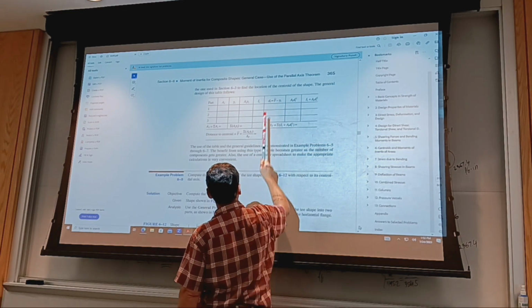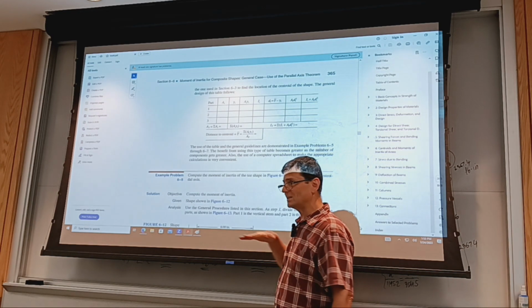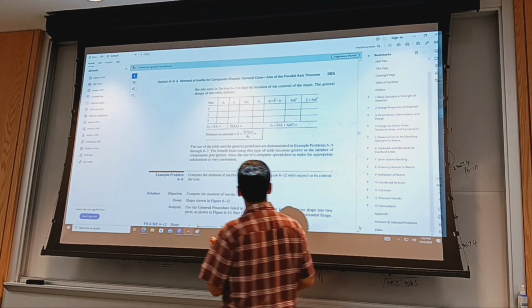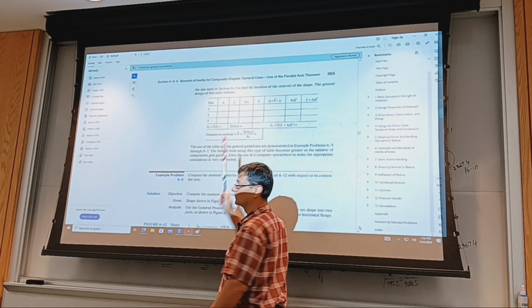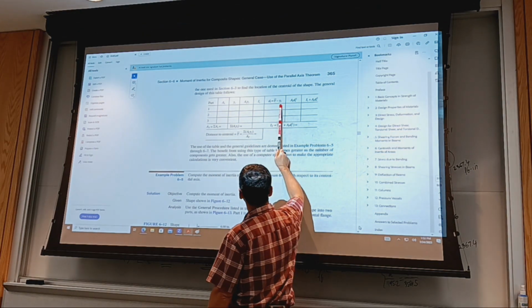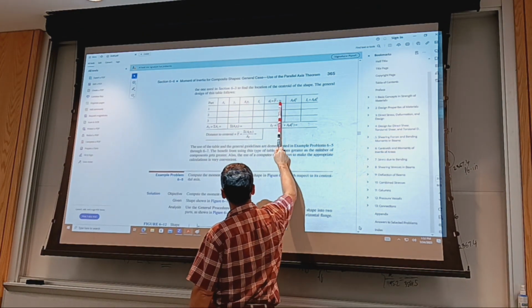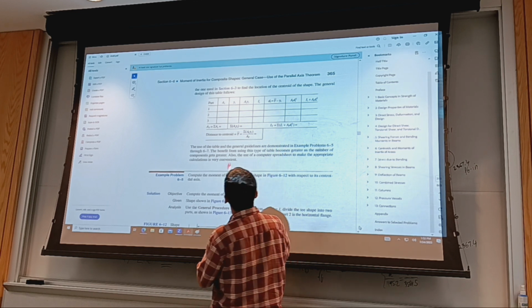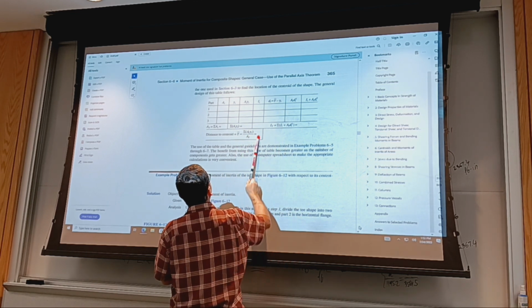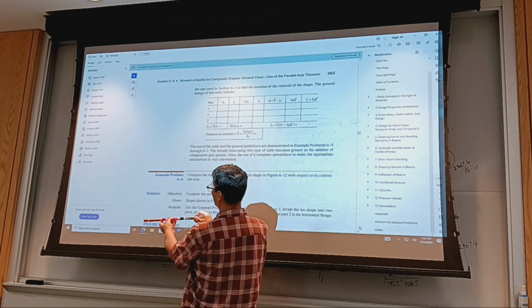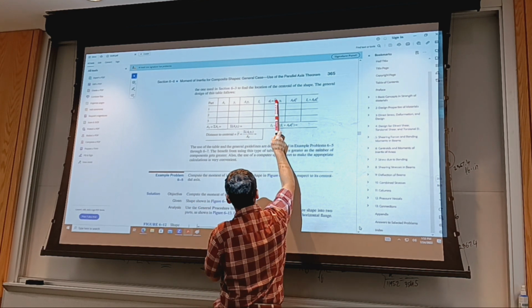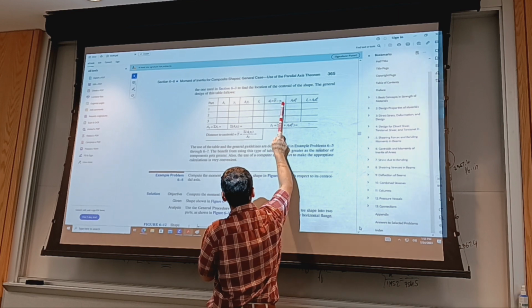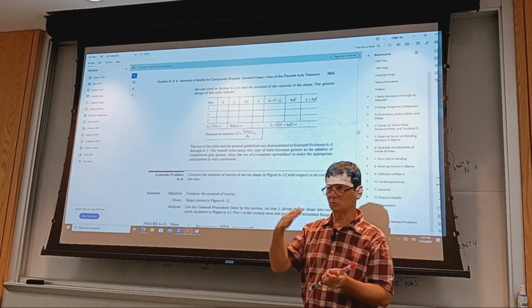You calculate the distance from the axis that you considered. Actually, no, let me back off a little bit. So you see here the centroidal axis that you have, you know where it is now. So you started with an arbitrary axis, now you move to the centroid, and you calculate the distance from the axis through the centroid to the centroid of the individual pieces.